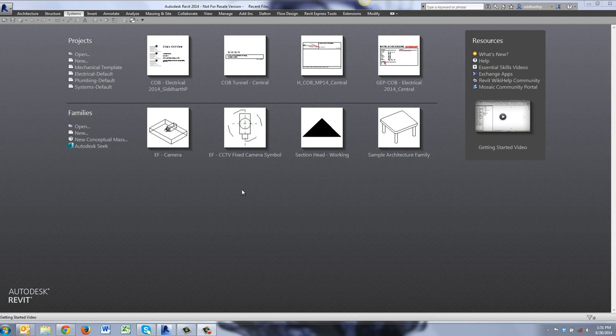Connecting panels through feed through lugs. Oftentimes, when you have one panel feeding another panel, you do not want the panel that is being fed to occupy any breaker spaces on the source panel. So we'll be looking at a workaround for that kind of scenario.